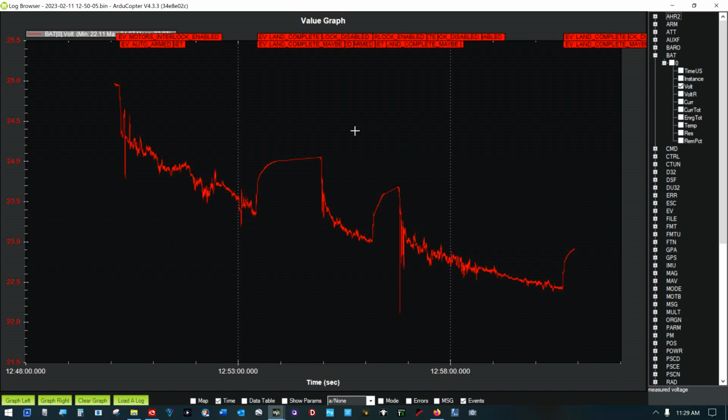Therefore, this is one contiguous data flash log instead of 3. If you disconnect the battery when it's on the ground, it will be separate. So the battery started out up towards 25 volts. This was when it was flying its mission and all that stuff. This was that second little flight I did with the radio failsafe. It takes place right in here.